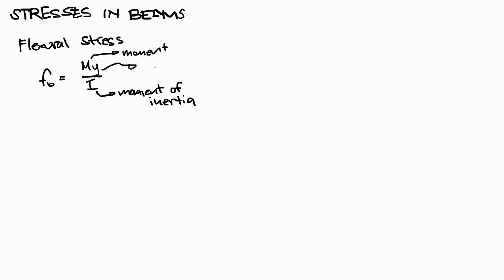Yan. And flexural stress or the stress due to bending, let's say it's F sub B, the stress due to bending is actually equal to My over I, where M is the applied moment. So, yung M, yan yung moment. I is what we call the moment of inertia of the section. Tapos, yung y, this is a distance. Okay, distance from the neutral axis.